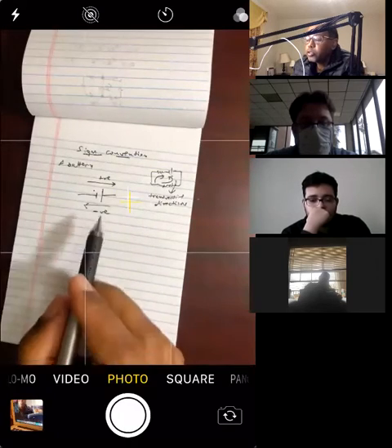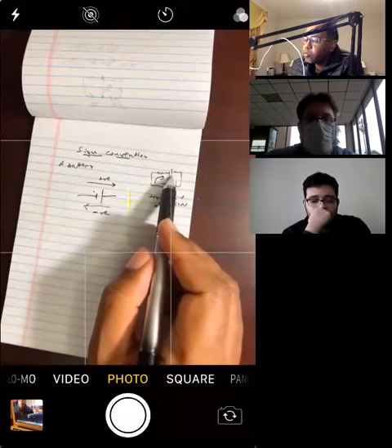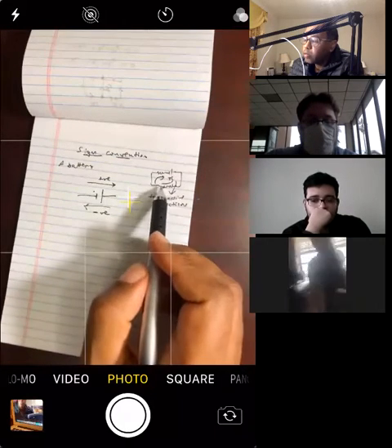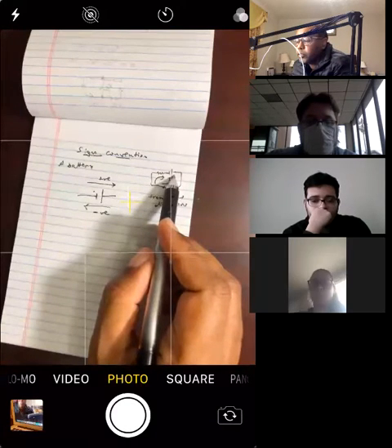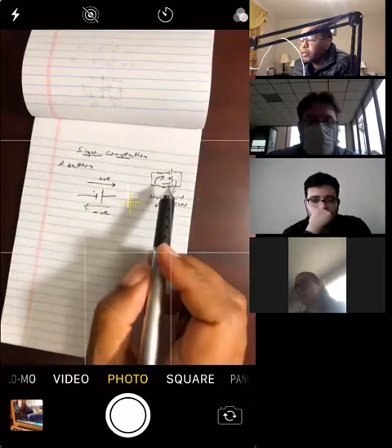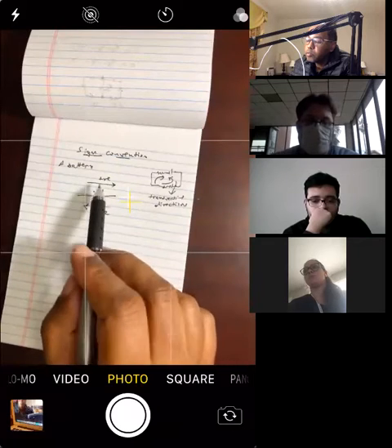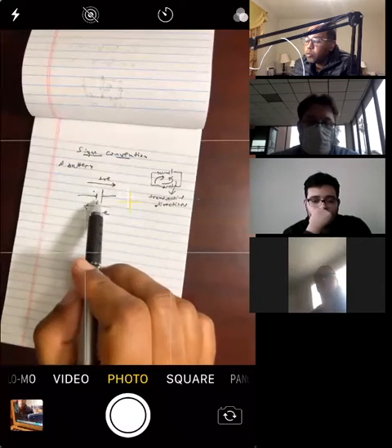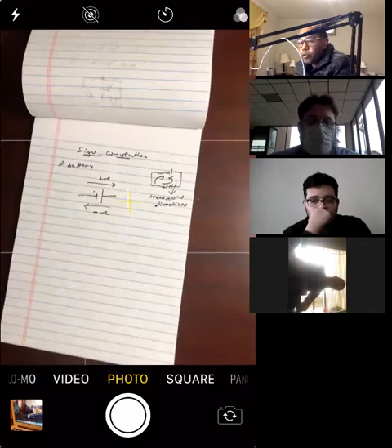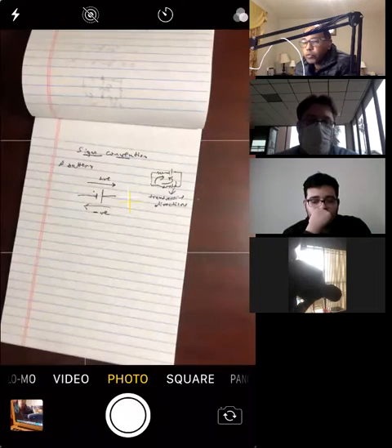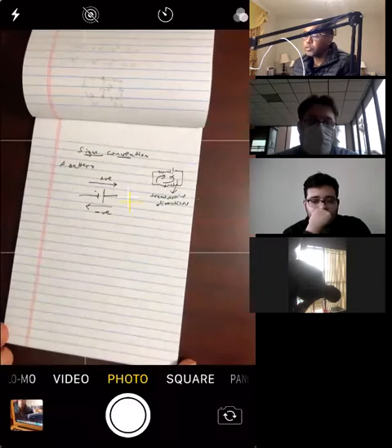That's why the traversing direction is important, because the sign conventions depend on which way you're going. So if you traverse the battery from positive to negative, take it to be negative. If you traverse it from negative to positive, take it to be positive.